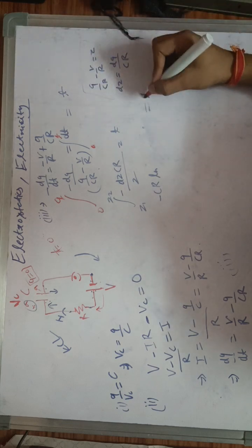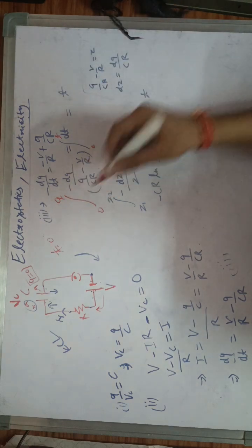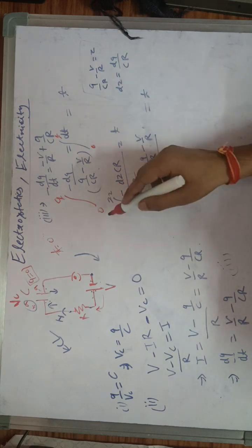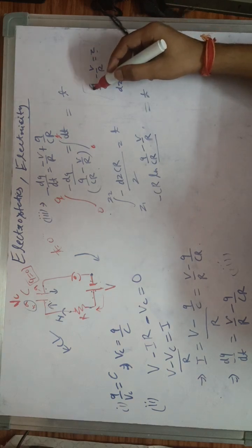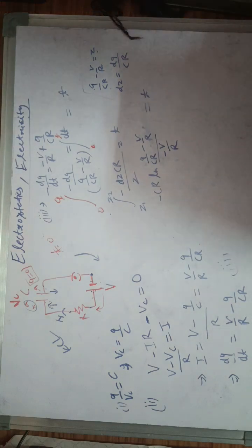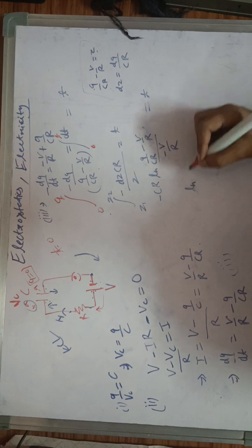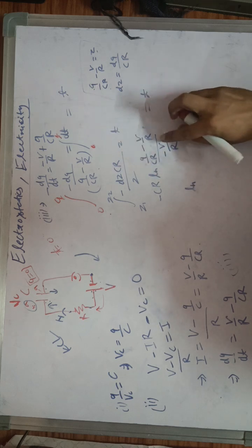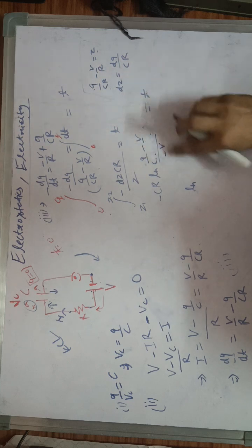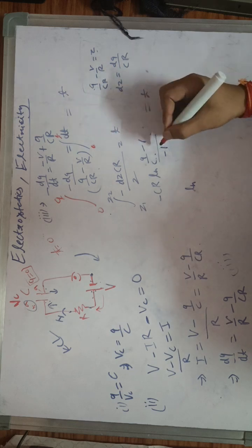Now I can write it as the final value of z is, the charge stored finally is q, so it will become q by CR minus V by R, and charge initial is 0, so z is equal to 0 by CR, this will give minus V by R. So now I can write ln of, now dividing this part with this, V R gets cancelled in both, and now I divide it by V, I get minus 1 here, this V gets cancelled and V gets here.